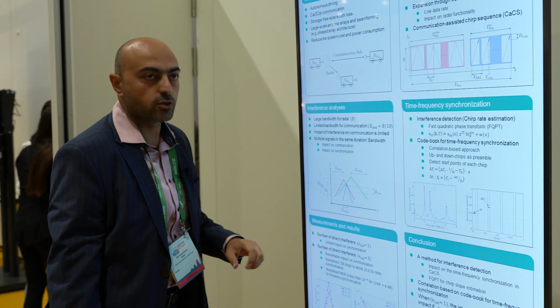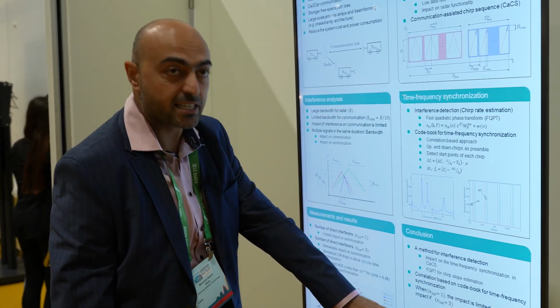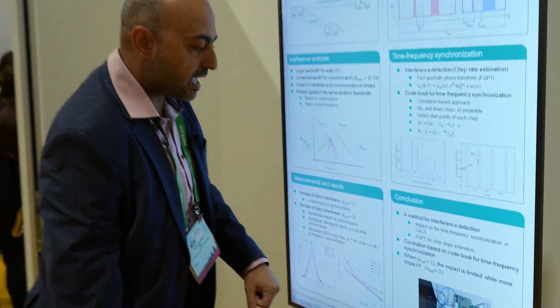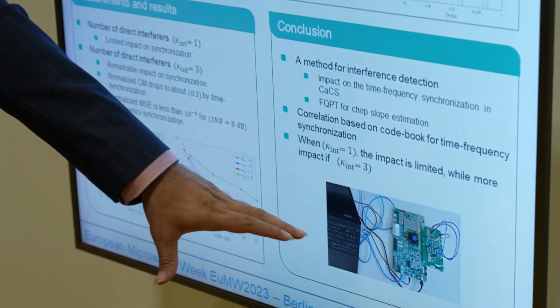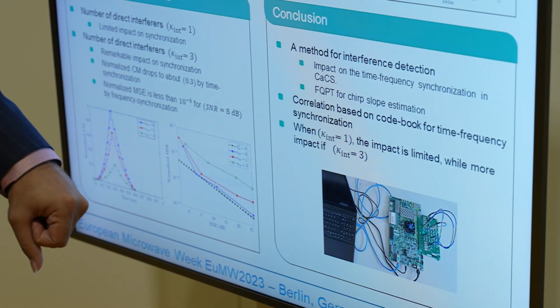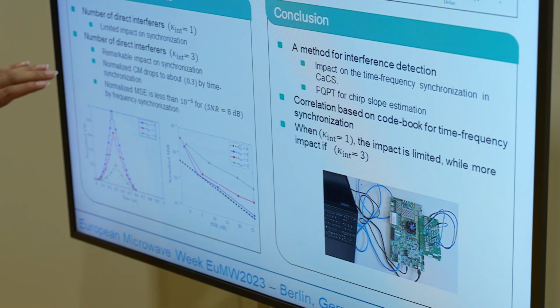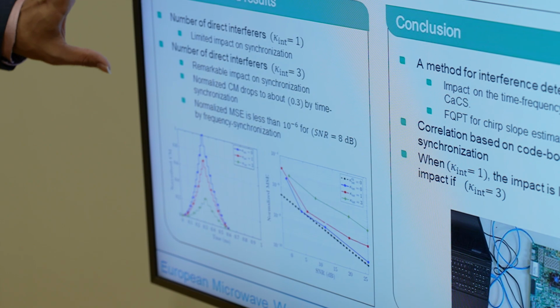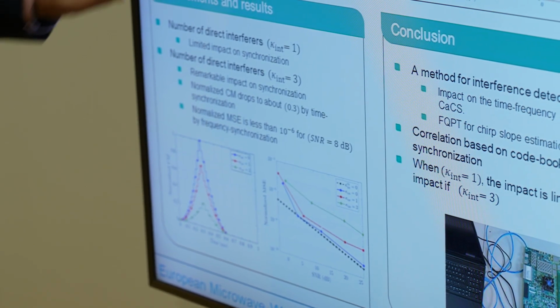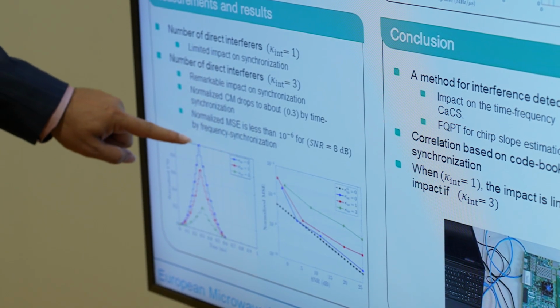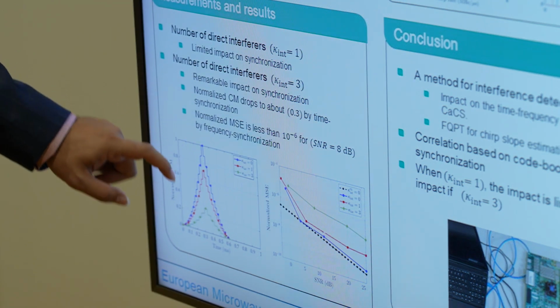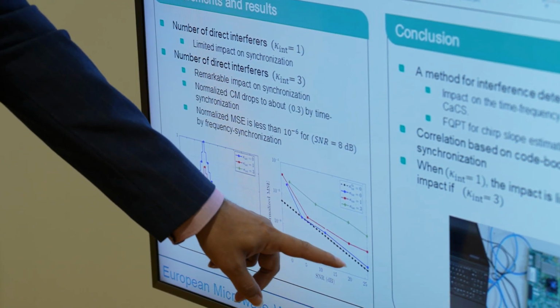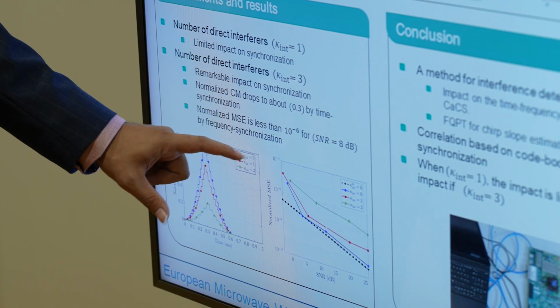For this investigation, we have been doing one measurement in baseband with 1 gigahertz, and with an FPGA from Xilinx company, and we investigate the frequency and time synchronization without interference. That means just with one signal, without the three ones here. And then we get a maximum peak for the time synchronization. And here for the frequency synchronization, everything works properly.